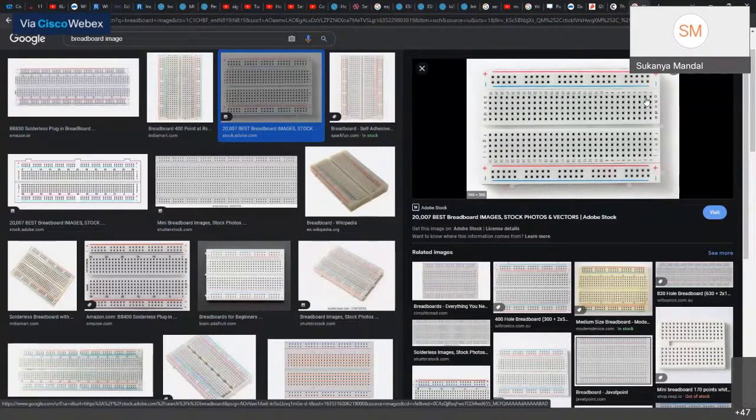So you can pull SDA and SCL from the Arduino to here, and then use these 4 pins to interface at least 4 sensors at minimum, or 3 sensors here, and you can short these 2, and then again another 4 sensors here. Does this answer your question?